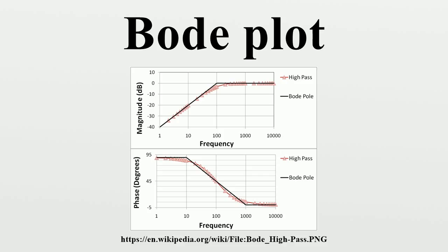Magnitude plot. The magnitude of the transfer function above, given by the decibel gain expression, then plotted versus input frequency on a logarithmic scale, can be approximated by two lines, and it forms the asymptotic magnitude Bode plot of the transfer function. For angular frequencies below it is a horizontal line at 0 decibels, since at low frequencies the term is small and can be neglected, making the decibel gain equation above equal to 0.